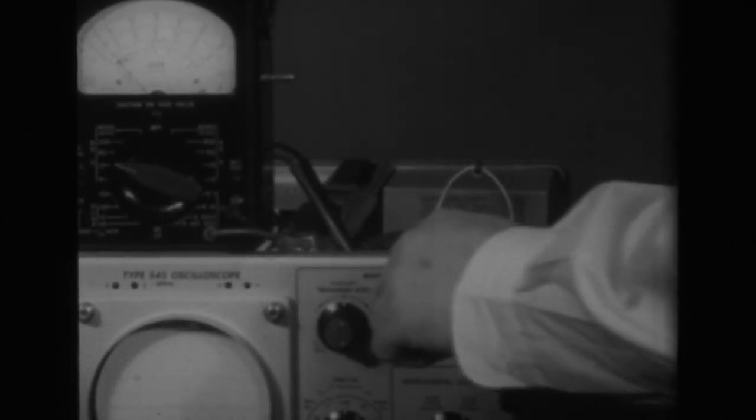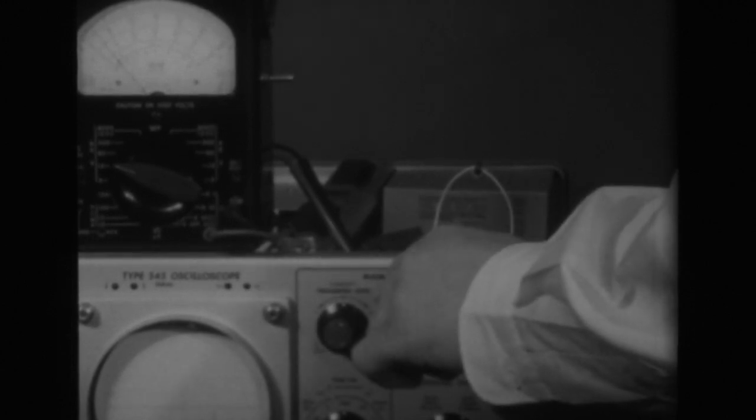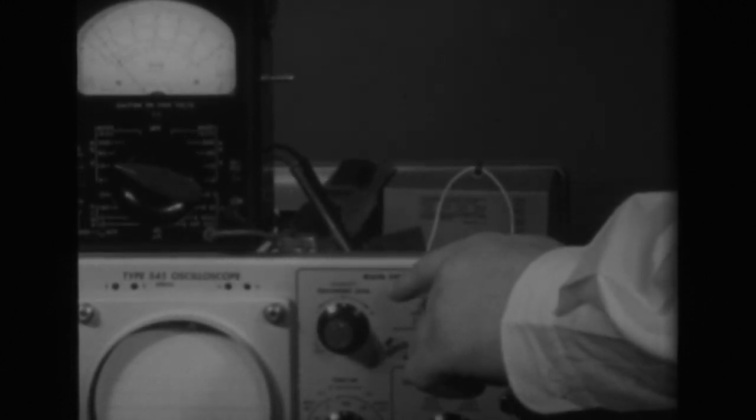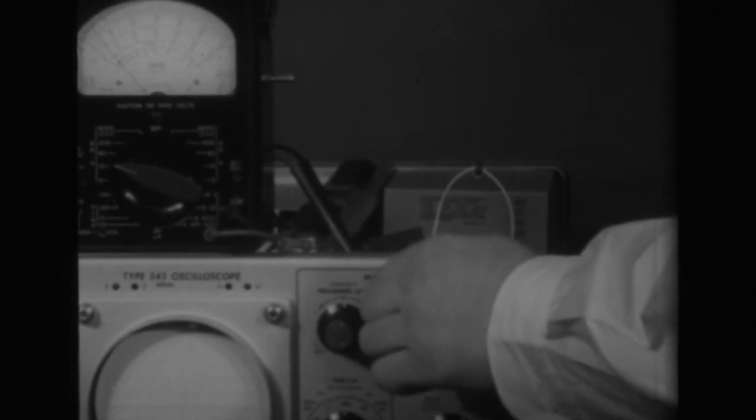This particular dial is quite close. However, if you do notice an error, loosen the set screw and turn the knob on the potentiometer shaft until you have found a location for the knob where the white dot stands opposite the 0 and the control is properly adjusted as shown here.